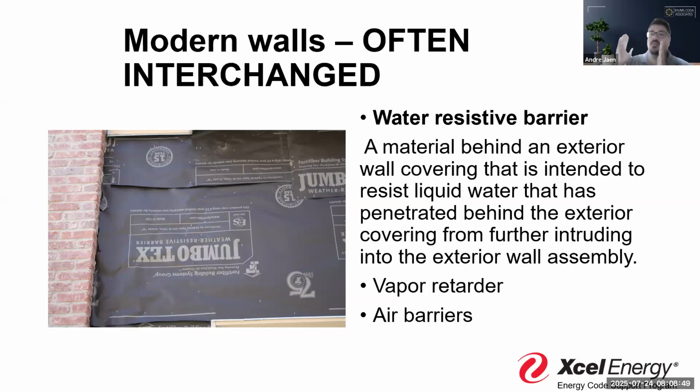So remember, this is the weather on the outside. This is the exterior water intrusion. It's not the same thing as the water we're going to make inside the house, right? We're going to have steam and humidity. We're going to have those things happening in the house on a regular basis. That's not that water. We're talking about liquid water that's not in that vapor format, but that driving rain that might be trying to penetrate the assembly.